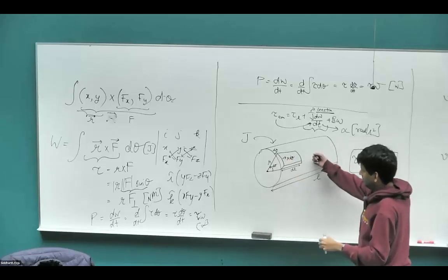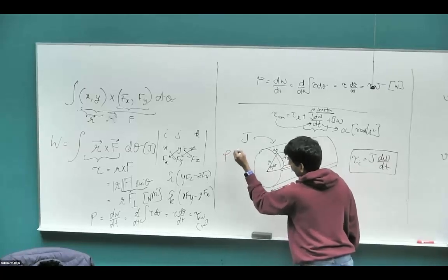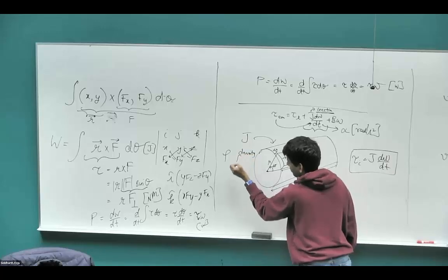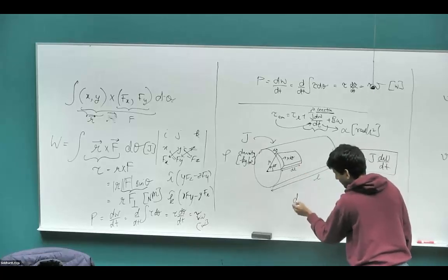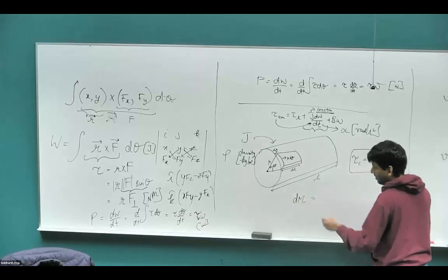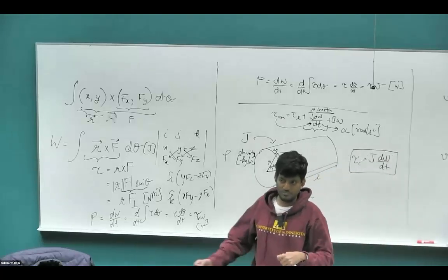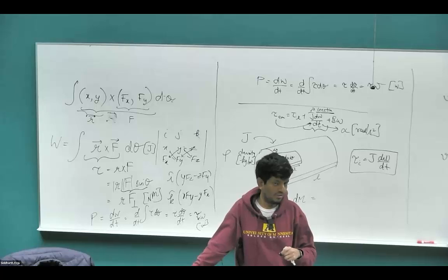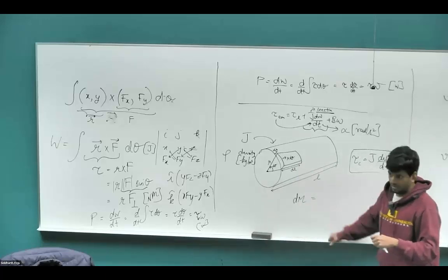And then the density of this shaft, we are going to call it rho, in kg per meter cubed. What is going to be the mass of this incremental volume? You have all the information there to figure out the mass of this incremental volume. The volume of that incremental element that I have drawn there.